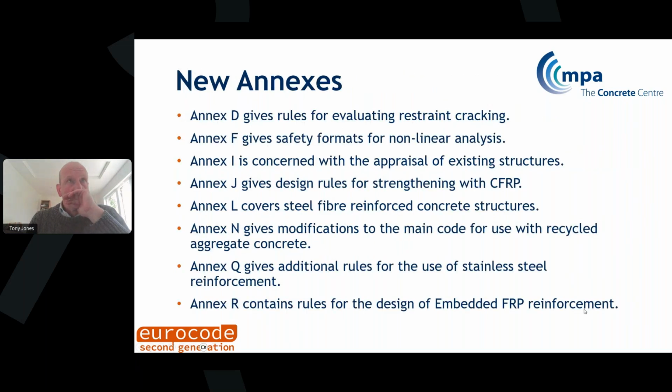Now, what we have got is a whole set of new annexes. So Annex D on restraint cracking, those familiar with C766 will recognize it, but it is somewhat different. So you need to follow it in full and not mix approaches. There are safety formats for nonlinear analysis, which hopefully will match eventually with the Annex coming in EN 1990. We have Annex I, which I mentioned previously, on the appraisal of existing structures.